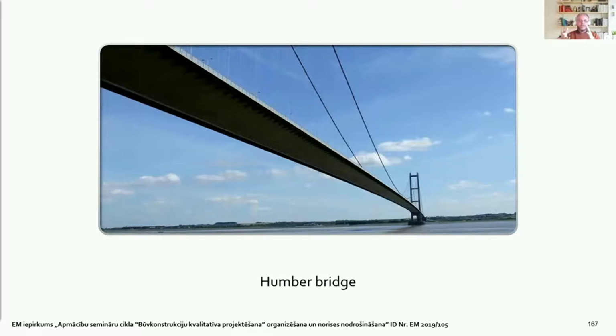With this structure, the cables deflect, changing geometry picks up the load and so on, and it is flexible, but it's so long it doesn't matter too much. If you're over in the middle, you might feel it bouncing around, but that is fine. It's within limits. But yeah, these non-linear structures do enable us to take much larger spans than a linear approach does.